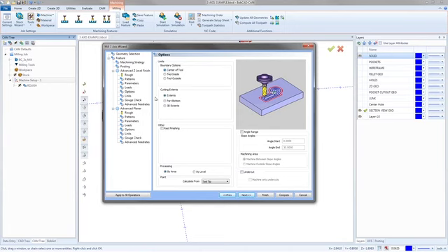All right. 3D Extents is a nice one to turn on if it's an option. It's an option in most of the 3-axis Pro toolpaths. It allows the center of the tool to pass the edge of the part or the edge of the stock a little bit more to make sure it can cut the part. Still has to listen to the boundary if you have one set up. So be careful with that one.